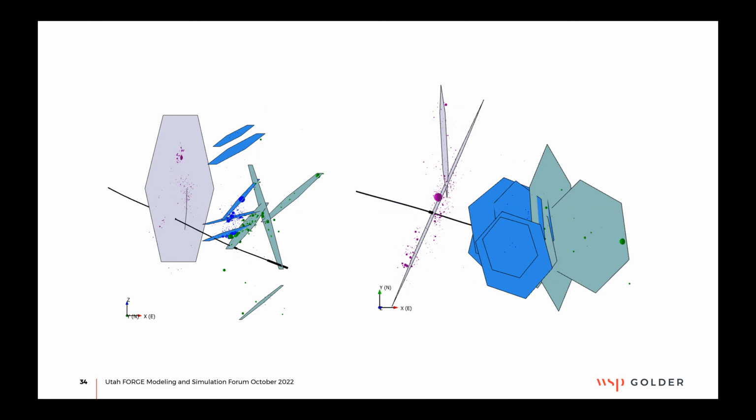I don't know. I mean, there's water in these features, and so I don't know necessarily what a dry versus a wet event is. I can explain what that means. A dry event means in the stress shadow around the fracture. So if fluid is going into one fracture, but it creates a stress shadow around it, then you could create microseismicity purely from the stress shadow. That would be a quote dry event, even though you're correct, it's not actually dry, 100%. Fair enough. Okay, moving on, next question.